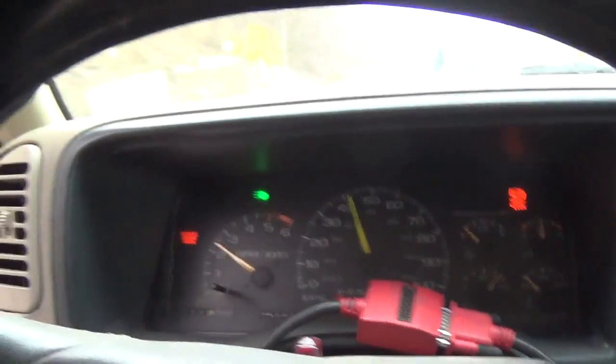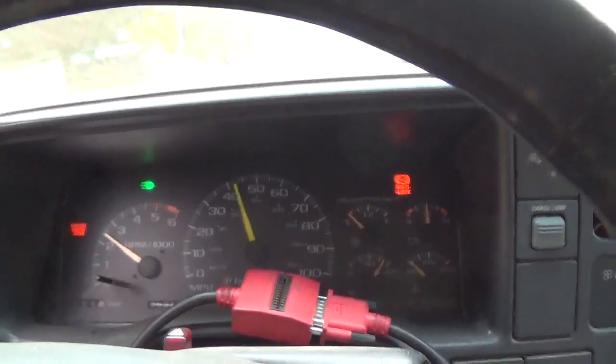That's where the service engine light's on, but that's the least of this truck's problems. So let me see if they want to go further. I solved the initial problem of no power, but this cam retard is way off. 42 degrees is very excessive, so the distributor might need to be adjusted. The cam chain's probably stretched. Everything's probably worn like hardcore. So let me see what they want to do next.